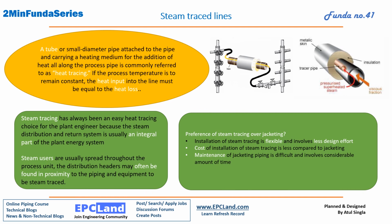Steam trace lines: a tube or a small diameter pipe attached to the pipe carrying a heating medium for the addition of heat all along the process line is commonly referred to as heat tracing. Okay, if you see here, there is a core pipe which is having fluid inside, and this is a steam tracer pipe which is further protected by the insulation cover.